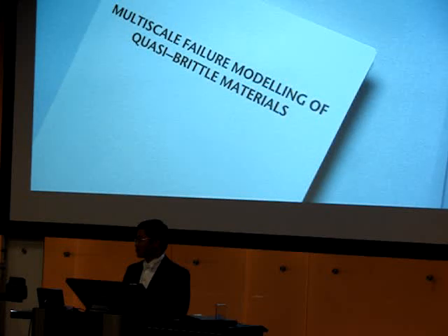You have in your discontinuous computational homogenization scheme a microscale where you have cracks, diffuse cracks, as you say, and you solve it with a non-local formulation. And on the macro scale, you have a discrete crack. You solve that with an X-FEM scheme. So you map a local diffuse pattern to a discontinuous crack, basically. But you can imagine that there are materials that react in the opposite way.